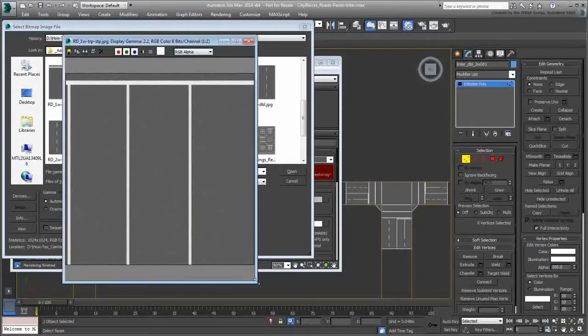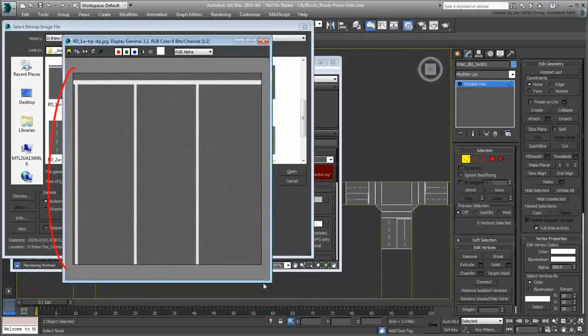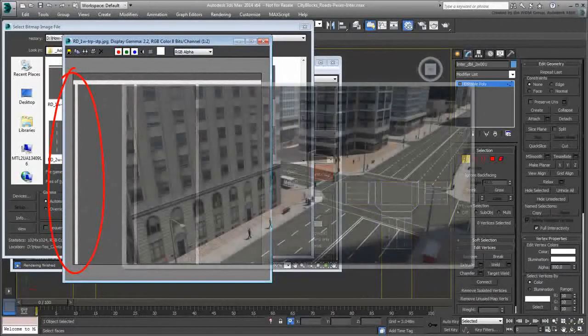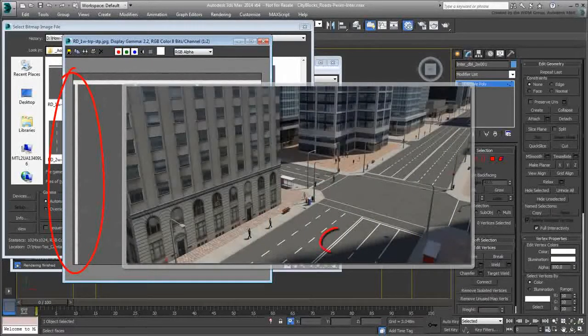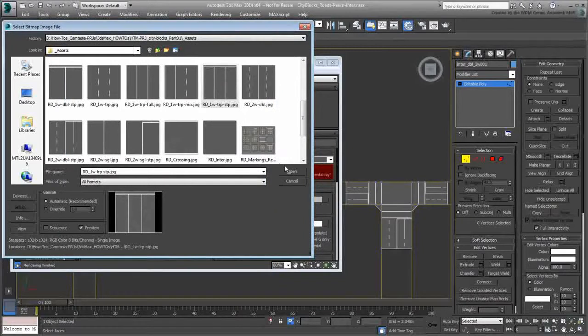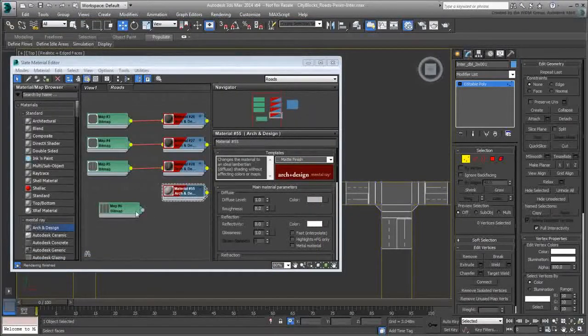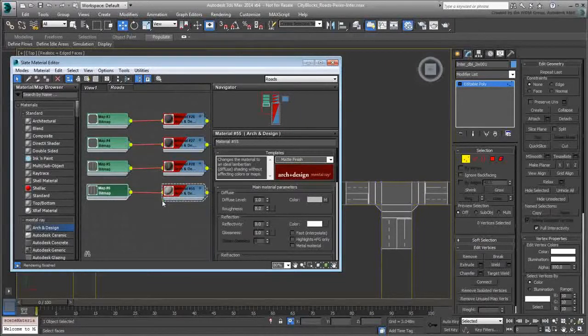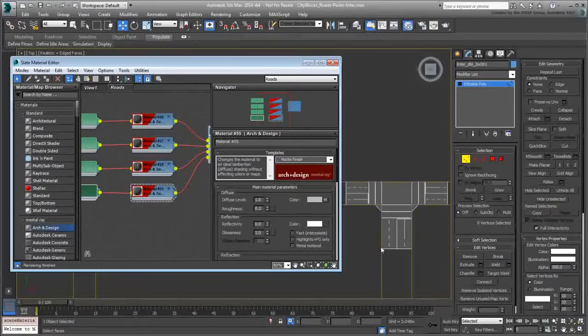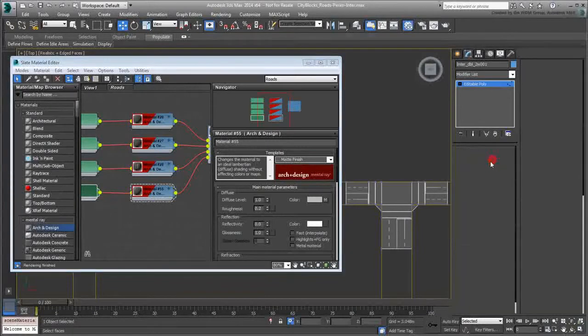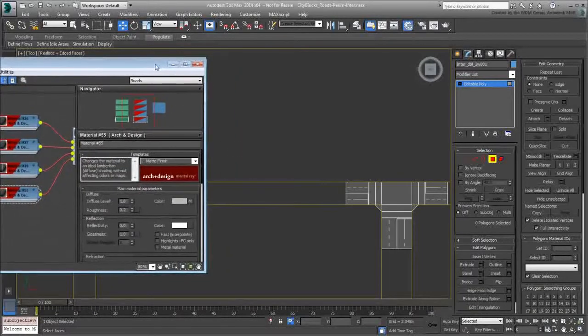Note that this bitmap was created with a side solid line. When you later tile this city block, you will have double line dividers between the 3-lane roads. Because the new submaterial is assigned to ID number 4, select the 2 squares with the wrong texture and assign them to ID number 4.